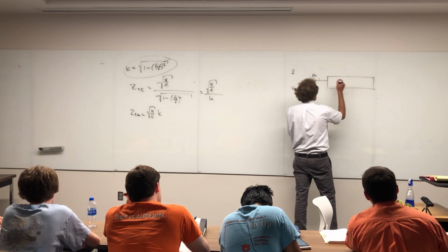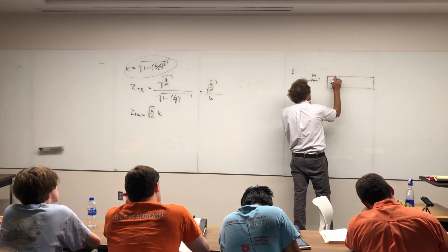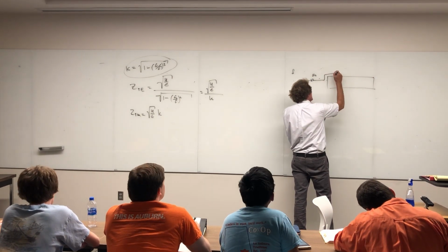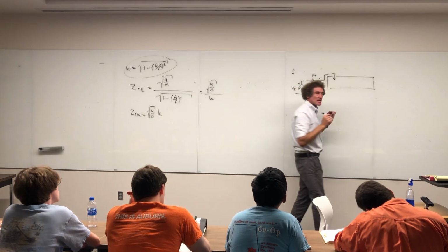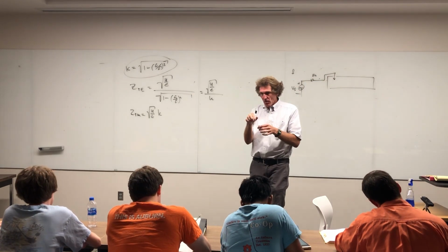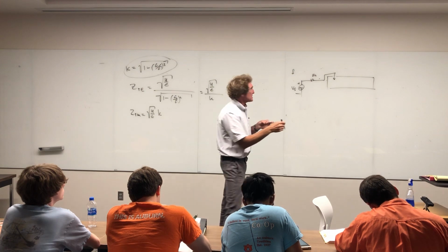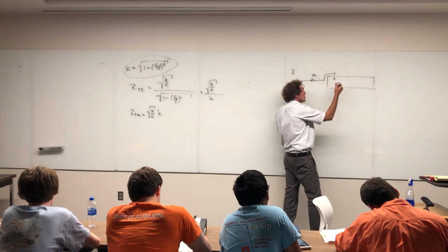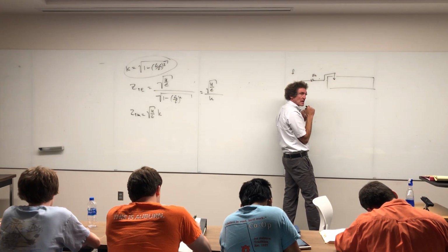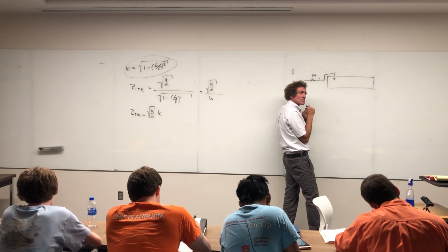I'm not even going to try to draw everything. The way these things actually are fed is they put a little feed antenna here. It's a short little antenna into the guide. They cut a hole, put it in there, and this antenna is set up so it will energize the mode of propagation, like the 1-0 mode. And I'll get to the actual field patterns later.